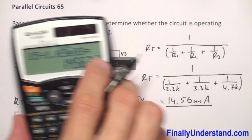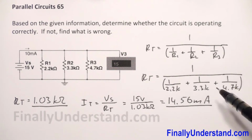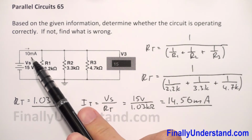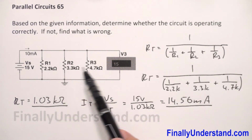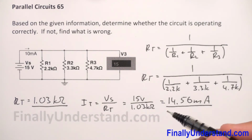Please notice that the current which I just obtained is different than the current which is in my circuit. So it means that there is something wrong with these resistors. One of them is probably shorted or open. We're supposed to verify what's wrong with them.